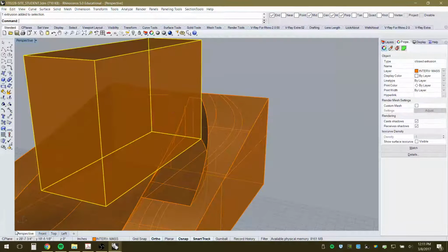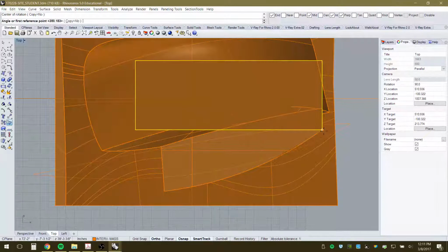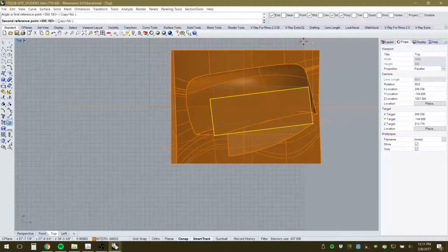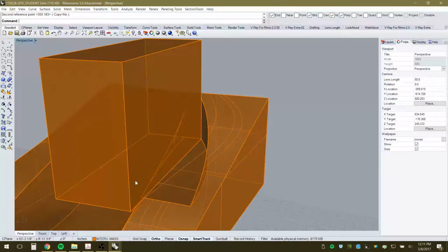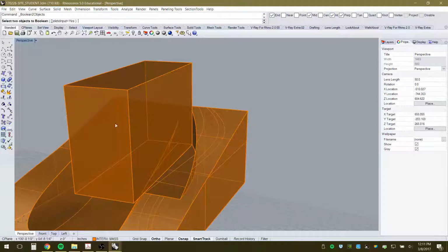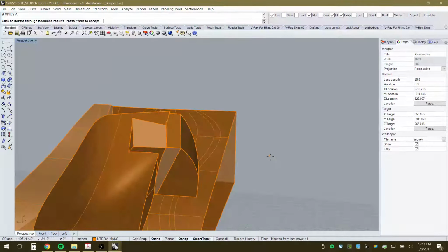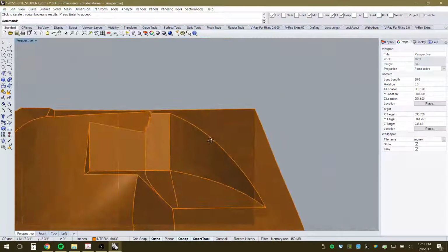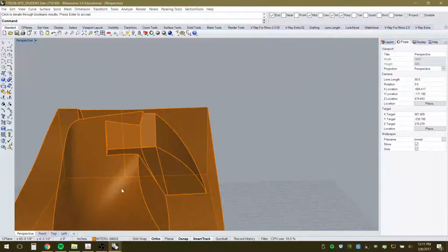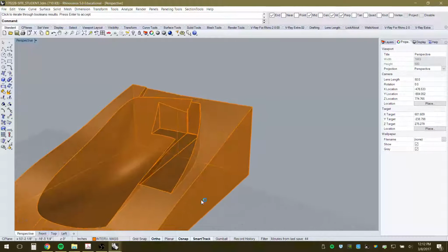I'll go ahead and select this, go into my top view, and I will do a 2D rotate. Shift key down. Okay, just getting that edge. And now I could go through the Boolean command again. Solid. Boolean two objects. 1, 2. Click through these options. And yeah, let's say that's good for now. I'm not super happy with the way it slammed into this back, but for the purpose of this exercise, maybe that's useful. You can imagine maybe stairs go up to this or come down from here above somehow, and then you can get over into this exterior space.